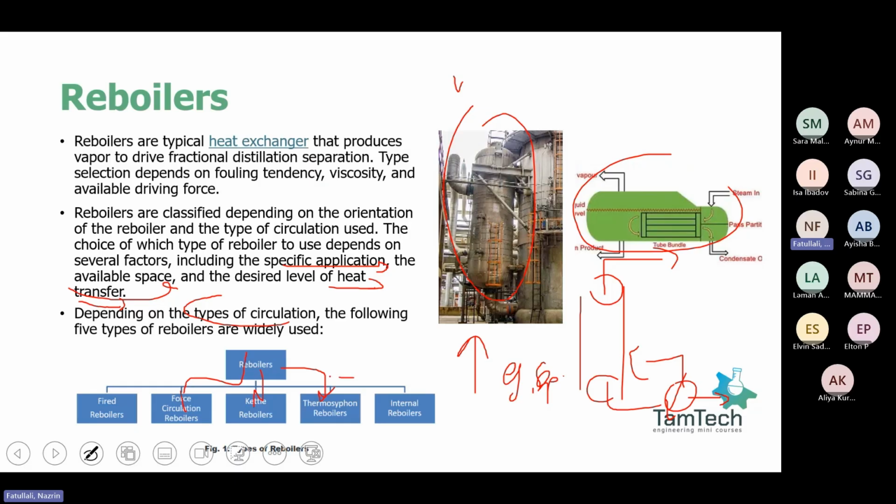The thermosyphon one is the most common, because here natural circulation is driven by density difference. It means that your boiling fluid rises, but cooler fluid falls based on the difference in density. Here we have a continuous loop without a pump, as the hot fluid rises to the top, but cold liquid is always supplied from the bottom.